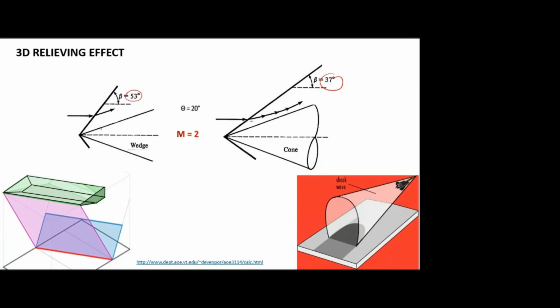And another thing, here the surface is 2D, the flow is also 2D, and if you see the streamline, we know always behind the oblique shock, the flow will be deflected parallel to this wall, and this flow will be like a straight line. Okay, this is 2D in nature, so this flow will be like a straight line. As it is a straight line, if you check the pressure distribution, it will be constant everywhere. Okay, so in this 2D case, the flow streamline behind the oblique shock will be a straight line, so it is producing constant pressure throughout this surface.